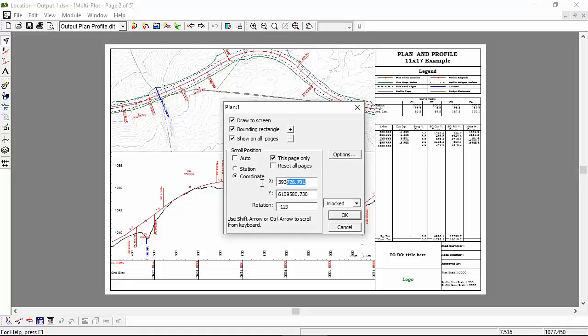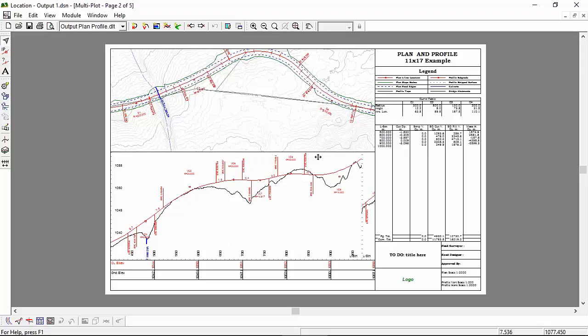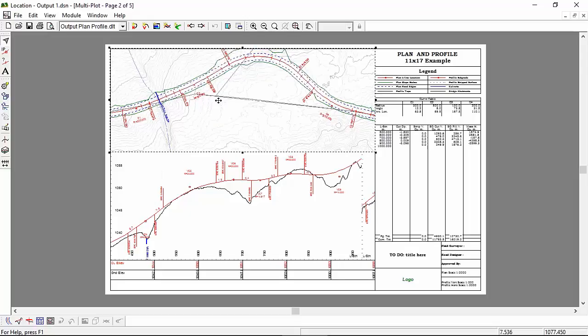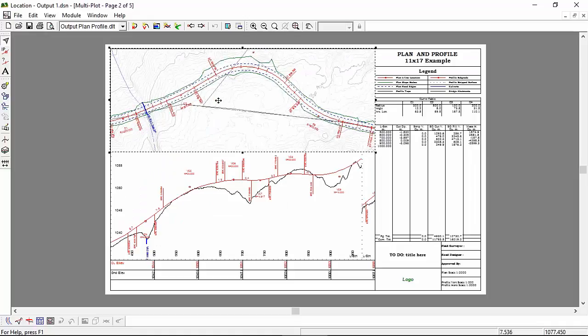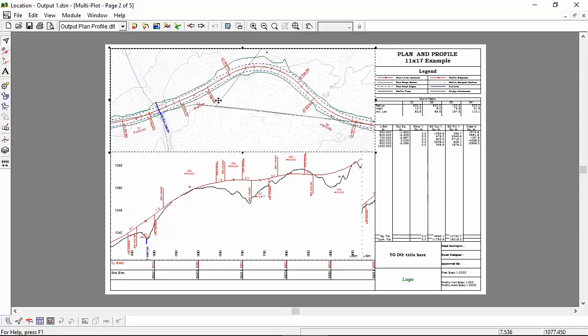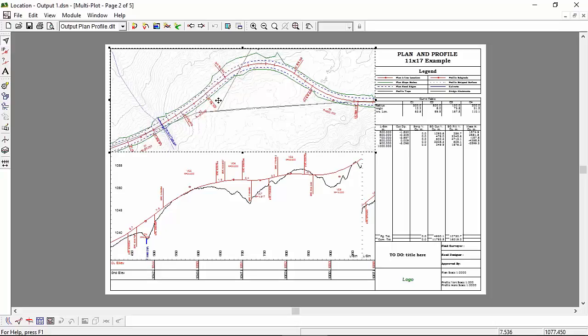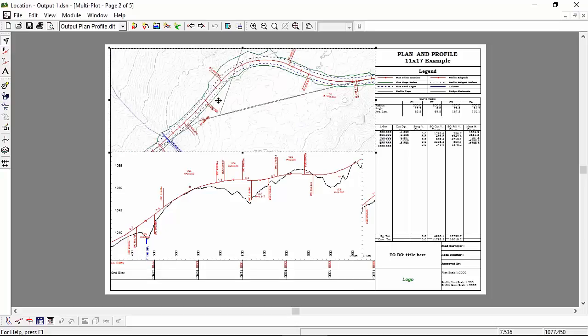Now it's kind of hard to figure out what numbers to type in here. So rather than typing in a bunch of large XY coordinate numbers, I am just going to scroll up using keystrokes. Now there's a way of doing that, but we've introduced, yeah, that's fine, that works. Okay, Shift arrow is scroll. Doesn't matter which way you scroll. Okay, so I've Shift arrow down a little bit, and Control arrow is rotate. So you can put it, oops, there.